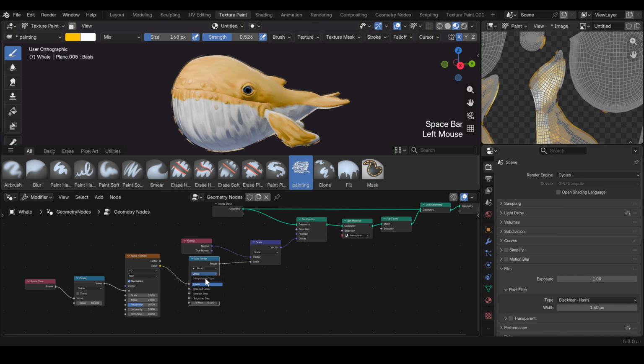But one more thing I like to set up is using not just the linear interpolation, but the stepped linear interpolation. This way it looks more similar to stop motion animation. I set the roughness to a higher value, and here I maybe increase the from max value a bit. You can see the noise becomes a bit more evident.